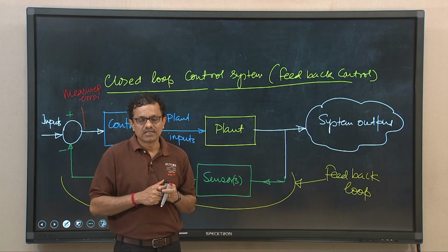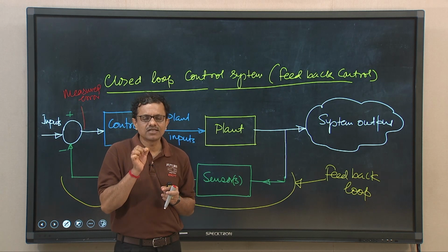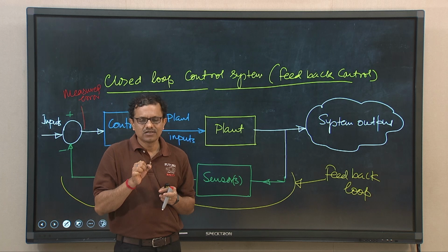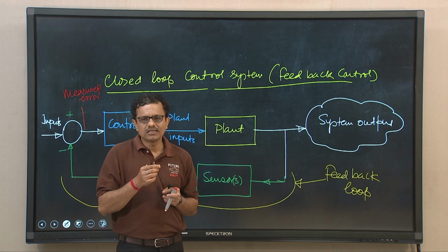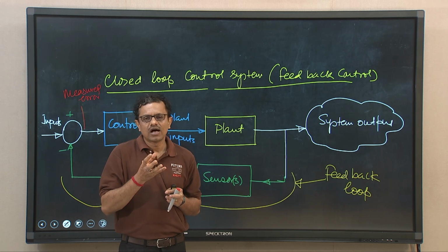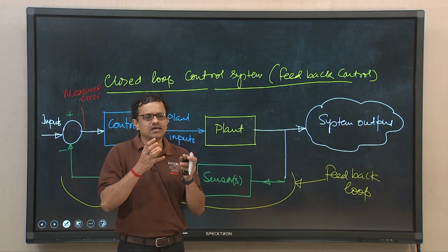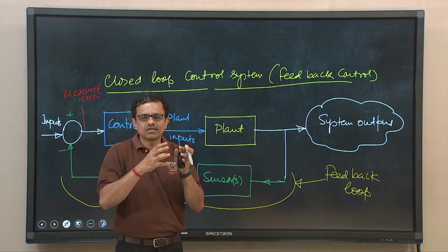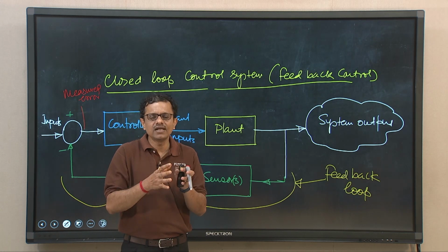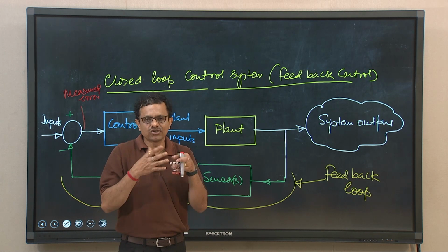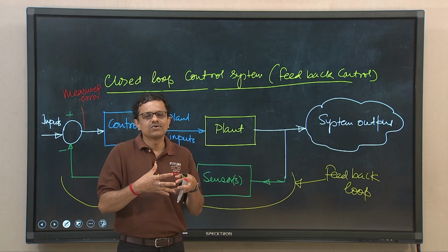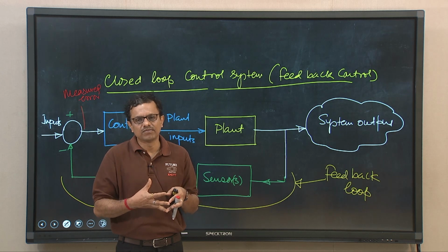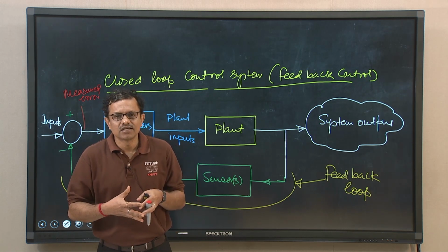So, this is the idea of a closed loop control system. That means, by sensing the oxygen concentration in the combustion gases with the exhaust gas oxygen sensor, the ECU will be able to control either the fuel injection period or the throttle valve, so as to maintain the air fuel ratio always stoichiometric, ensuring combustion is proper, and in such a case the catalytic conversion efficiency will be optimum. So, this is very important to know.